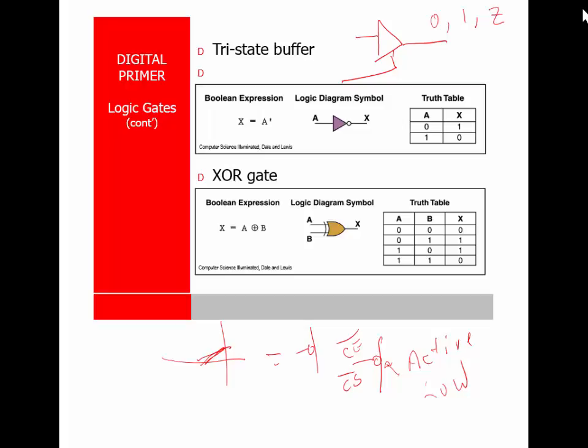You want to be able to switch this one on, but then when I go out, I switch this one back off. And then when I come in the next time, I want to switch this one. If I put two switches together, then they both have to be switched on if they're set up as an AND. If it's an OR gate, either switch is on, so I've got to turn this switch off, then go over and turn that switch off. But if I do it as an XOR, it works as a two-way switch.